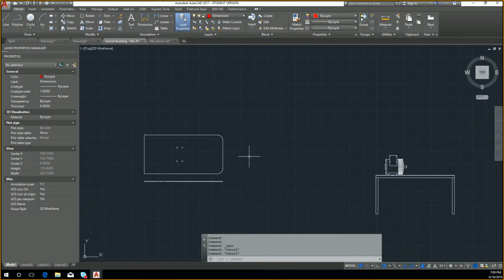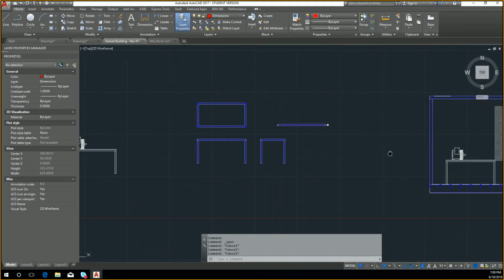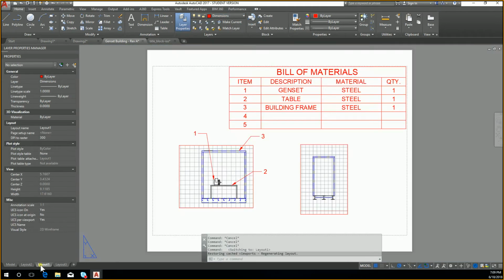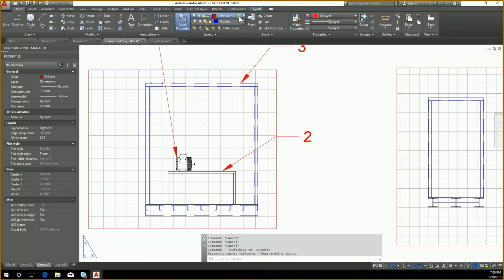So yes, it may be more complicated, making 20, 30 layers and then handling your layout space and start turning on and off your layers by freezing, because just last class someone brought that up. They were asking how to freeze, right? That's where if you were working with one model and throw specific layers away, you could perhaps protect yourself to some degree. Of course, this is within reason.